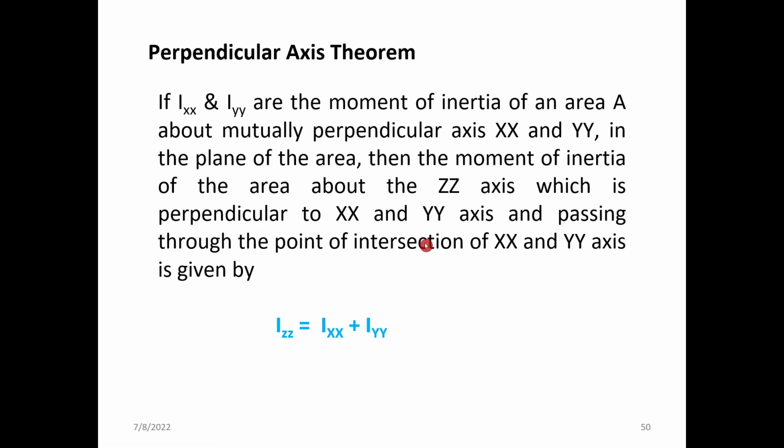Another important theorem is the perpendicular axis theorem. We discussed the moment of inertia about the y-axis, Iyy, and the moment of inertia about the x-axis, Ixx. If Ixx and Iyy are the moments of inertia of an area A about mutually perpendicular axes x and y in the plane of the area, then consider the moment of inertia of the area about the z axis, which is perpendicular to this plane. Maybe for the screen, consider a mobile screen or the laptop screen: perpendicular to the screen you have the third axis, the z axis.